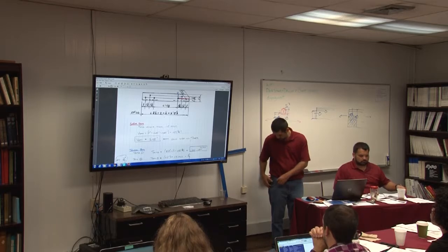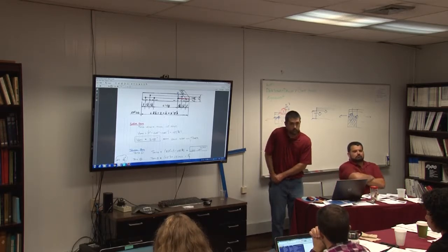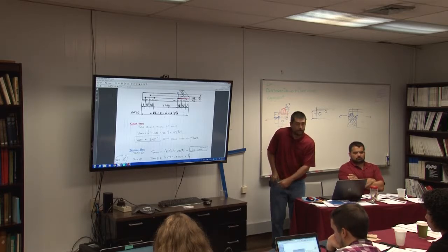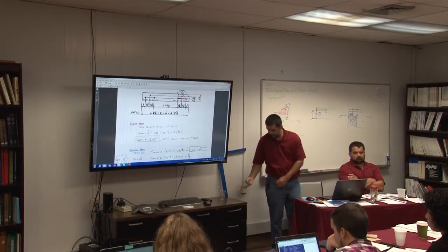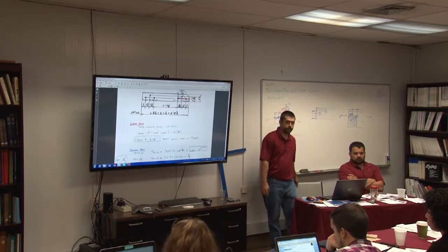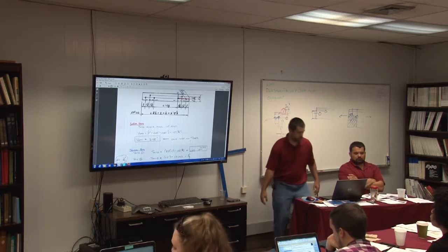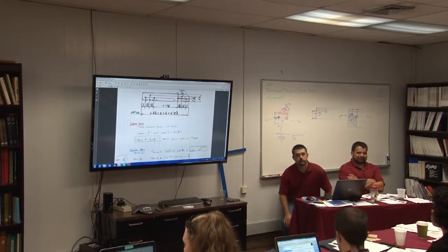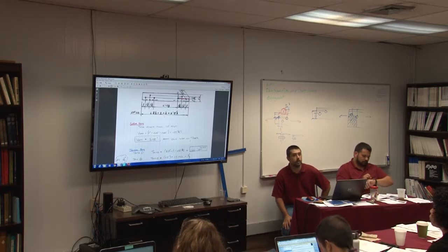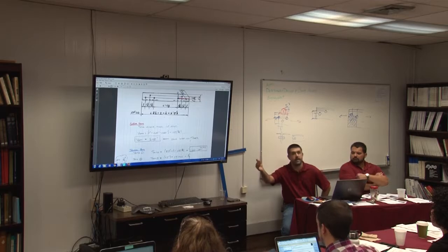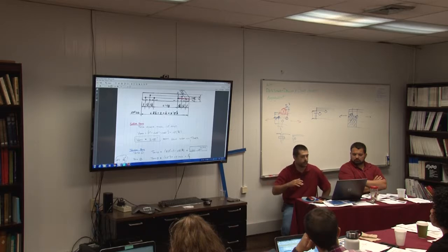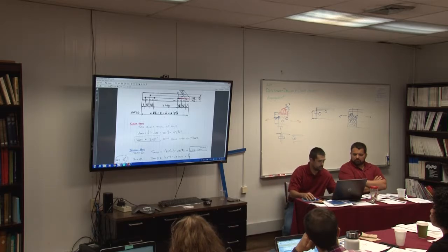And then it's comparing. How it's using that number is it's looking at that versus the loads that are being applied. Right. It's comparing the loads being applied to the bearing, the bolt shear, and the rupture, and net section, all of it. Whatever's the limiting factor could show that it's over. Right. So the member is going to get a usage. If it's 103%, it means that the demand is 103% of the minimum capacity, the least capacity. Okay.